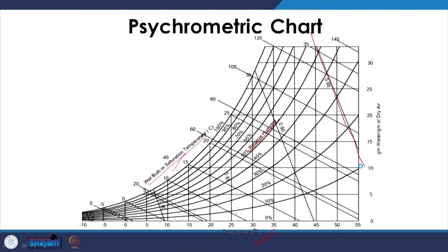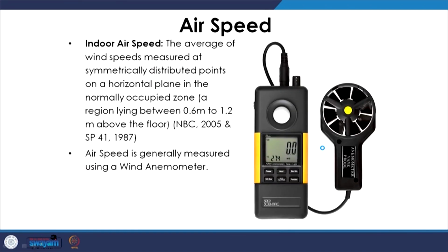Now, if we look at the psychrometric chart again, through the psychrometric chart very clearly the comfort range can be defined. We can define the thermal comfort range which is experienced by human beings. So, the psychrometric chart was a good way of demonstrating, experimenting and also defining thermal comfort, but not in a very comprehensive manner, as other parameters, for example the air velocity and the personal factors, could not be taken into account.